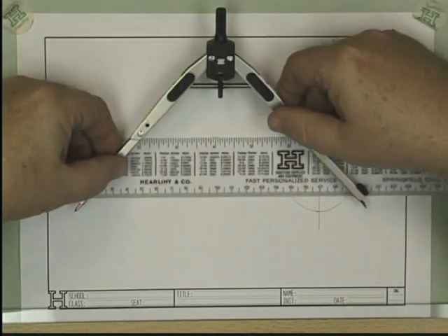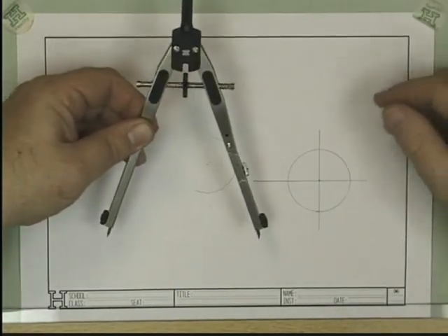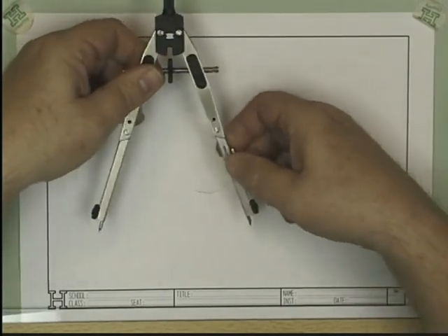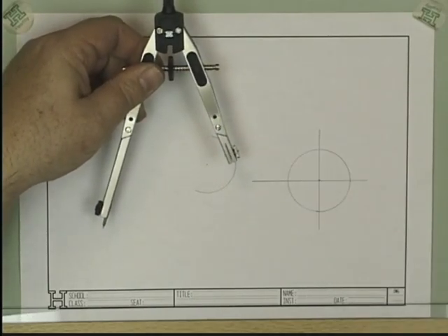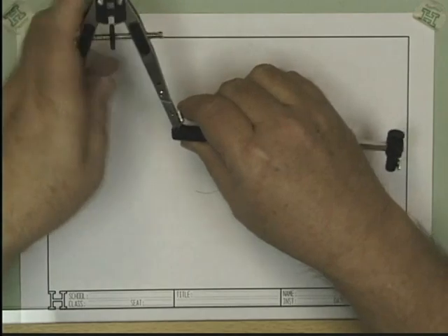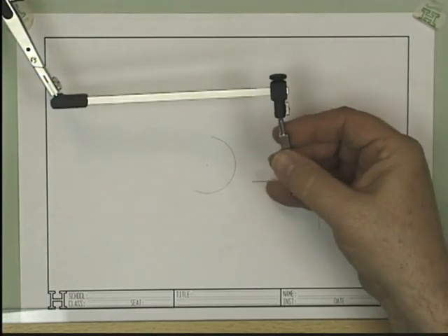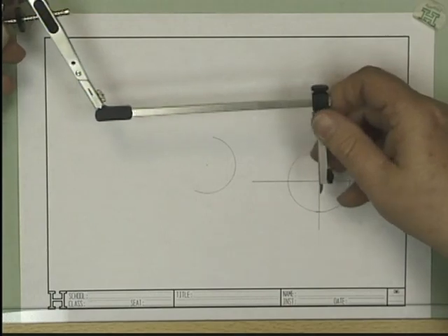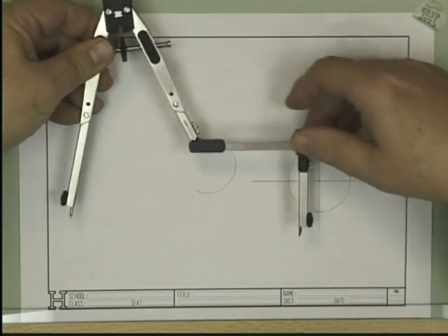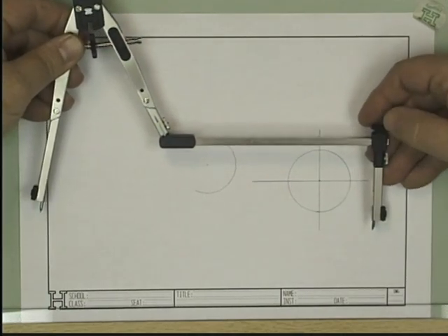But what if I want to make a circle that's even bigger than that? What do I do? Well, we have another instrument that allows us to make very large circles. And this instrument is called a beam compass. This particular compass, because I can remove this lead holder, can act as a beam compass. And what happens is I install this extra extender called a beam, like in a beam in a house. And out here at the end of the extender, I install my pencil. And this little screw here allows me to adjust the position that that pencil is on the beam. So you can see that now we've extended our radius out to a very large radius circle.